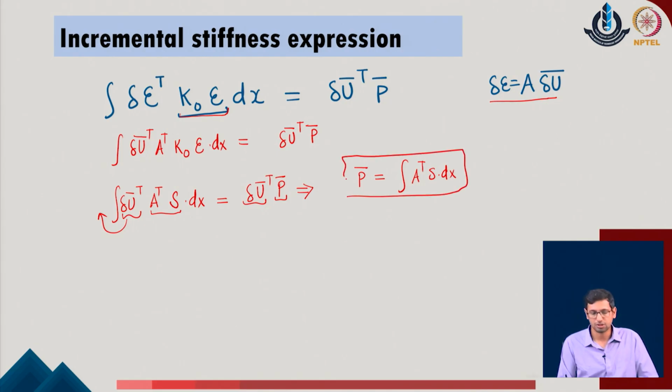So, this happens to be the standard expression which we utilize to correlate the nodal load values in terms of the internal stress values of the given system. We must recall that S in a general expression we have defined as a vector containing S of x and the moment component m of x in the given system.